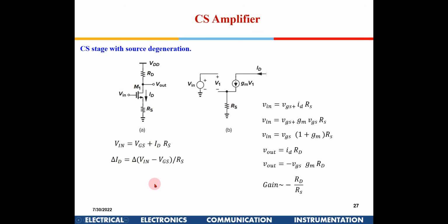I have a question. Yeah, ask me. This RS is not the replacement of the bias voltage which we generated with R1, right? That will be there. Yes, over and above that, I am putting one RS. This is the ripple we get from the VDD, and we can control it with this source degeneration. Correct. The other path between R1, R2 and VDD still exists. Okay, thank you.